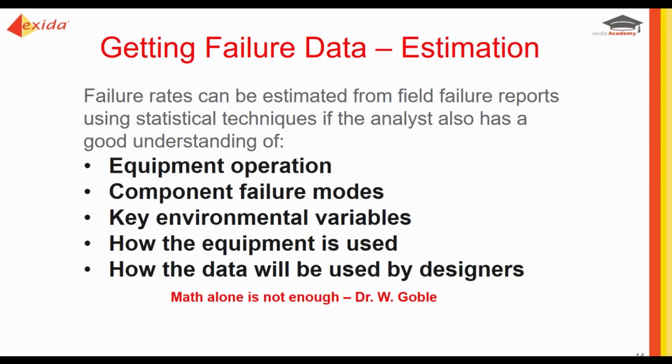So the first one we're going to dive into is the estimation technique, and it's a way that you can estimate failures from looking at field failure reports and using statistical analysis. But you can only do that if you have a good understanding of all of the equipment operation, the component failure modes, key environmental variables, how the equipment is used, and how the data will be used by designers. It's not just good enough to say, we've had 6 of these come back with an issue.